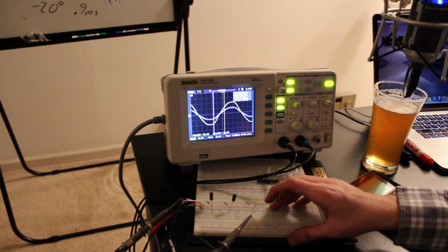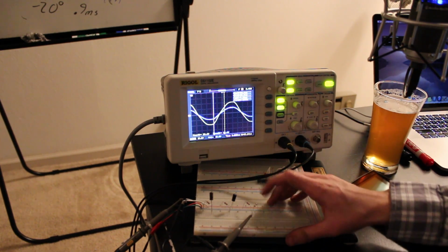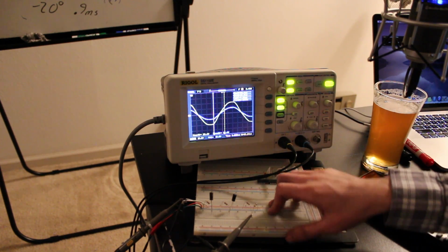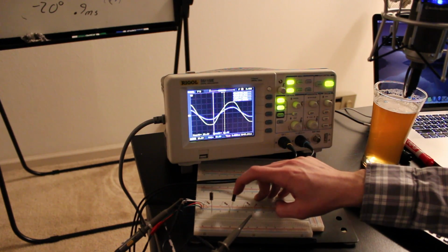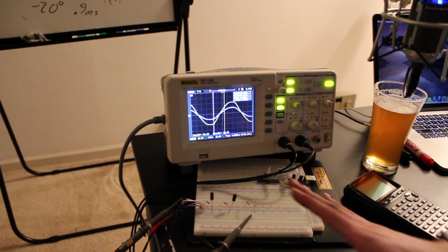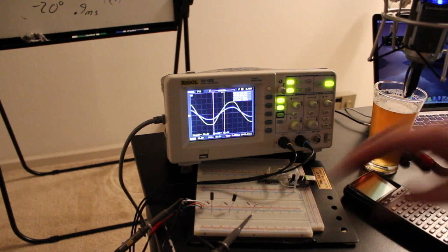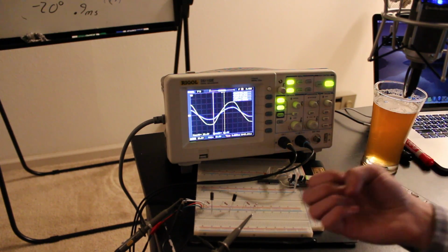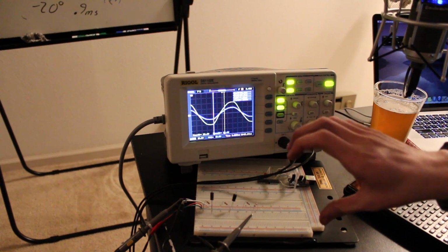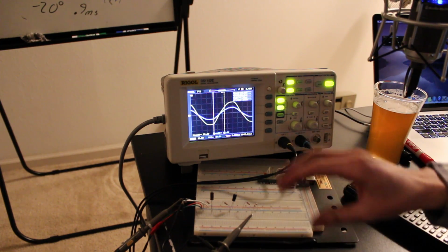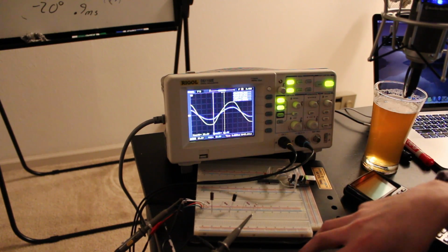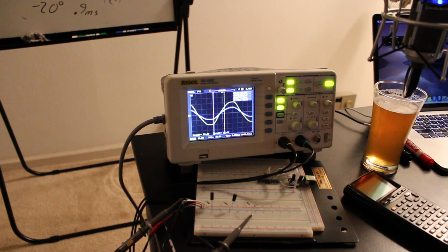We have a simple voltage divider, just a purely resistive voltage divider, two 1Ks, and we're measuring the Vout, just like I showed you on the whiteboard. Then we have a 1K with a 1 microfarad capacitor, and then a 1K with a 10 microfarad capacitor, all low-pass filters here. My input waveform is a 60 hertz signal. It's not the mains. I have it hooked up through a little wall wart that divides it down, so I have here on the scope a 20 volt amplitude signal, so 20 volt peak, 40 volts peak to peak.